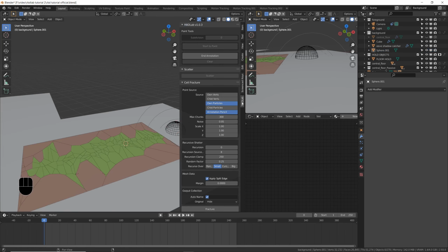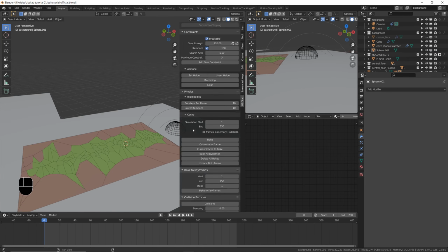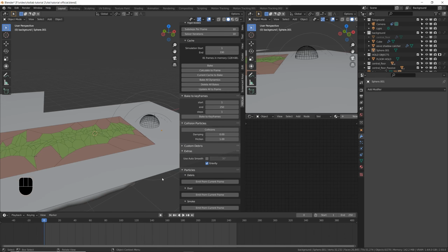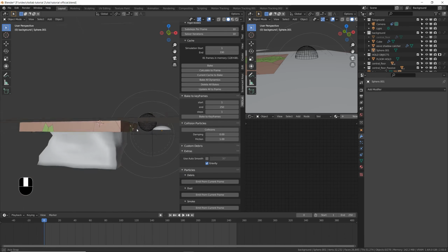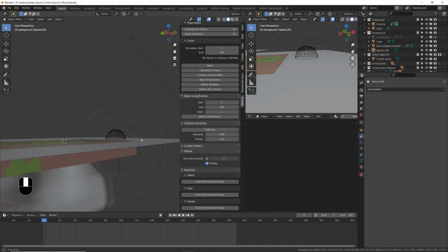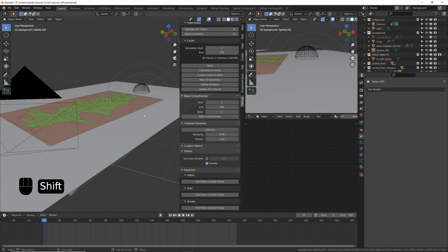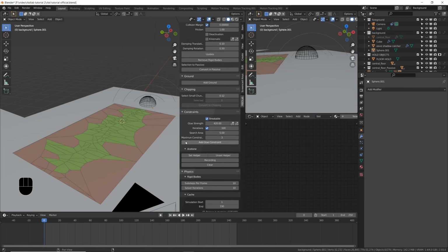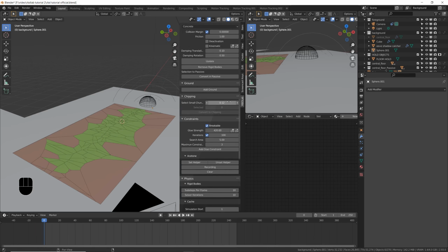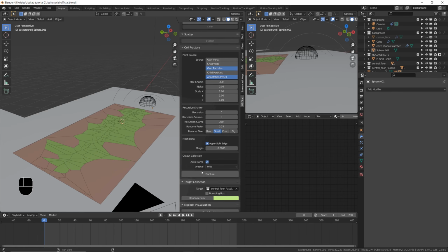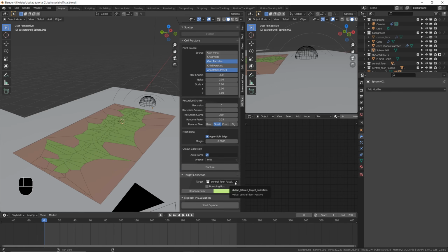So now, if you want, you can use the rbdlab to automatically add particles and chippings, but for this particular case, I prefer to do them manually because this is a particular type of fracturing. So I'm gonna ask the addon to help me just find the smaller pieces. Let's find the chipping panel, that is this, and if you increase the number, oh, maybe it's selected the wrong collection target. Yes, this is the passive.